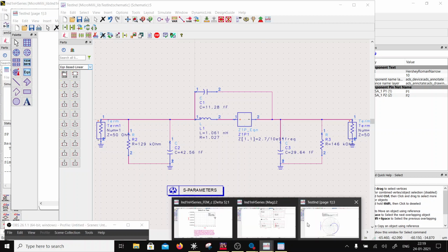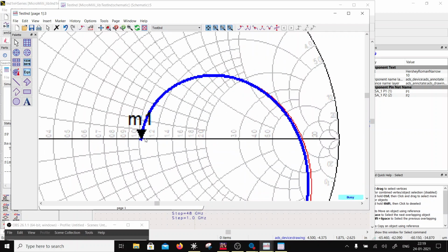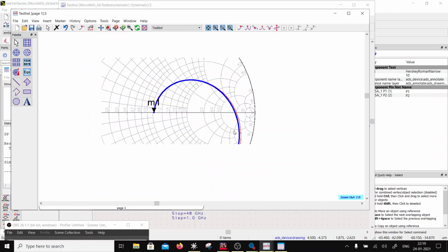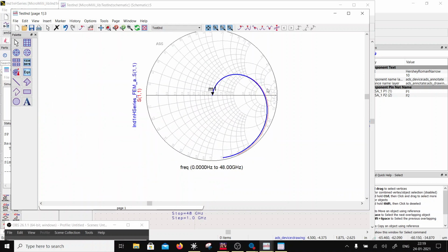So now it is starting at a right point, but there is this variation. The red one is taking longer to cross because the capacitance value is going down, isn't it? And that's why this extent is also less. So basically the capacitance value is doing this.